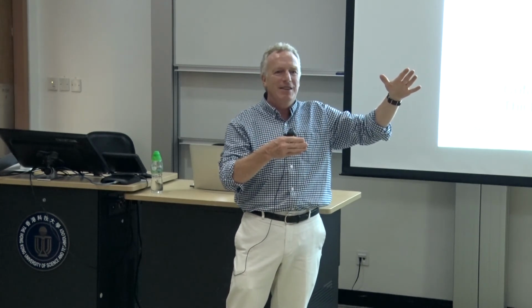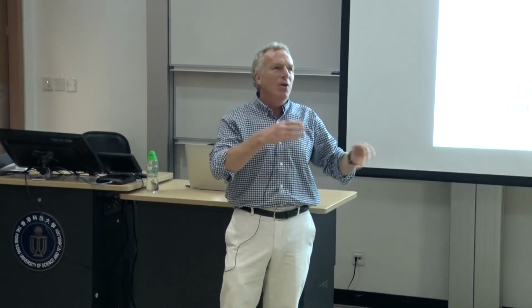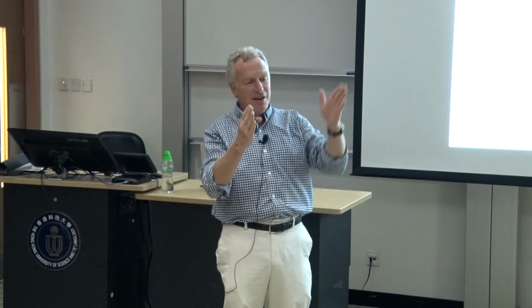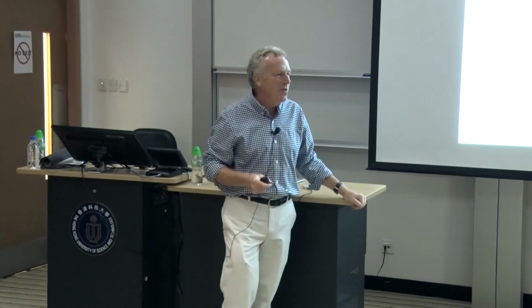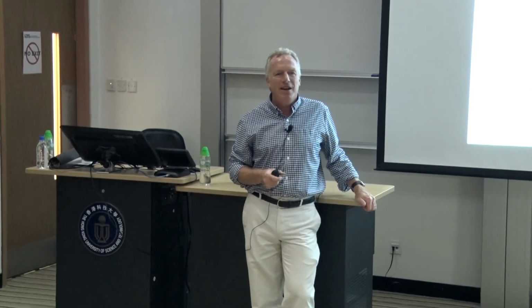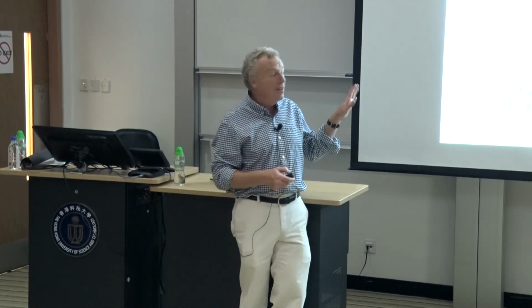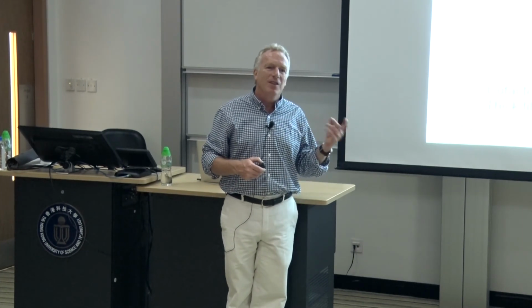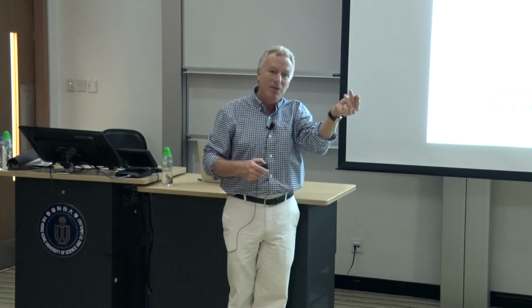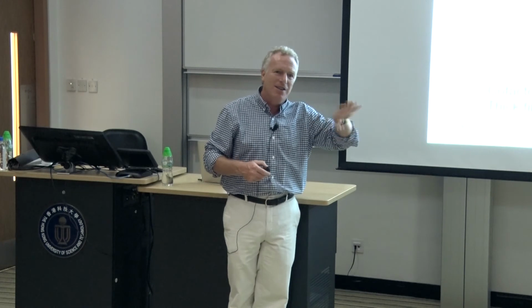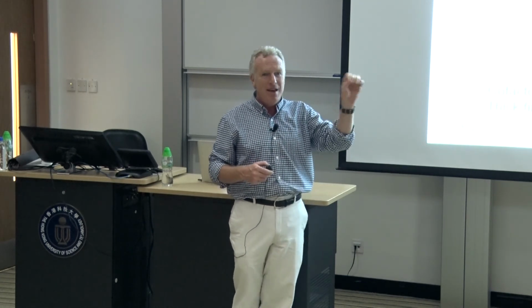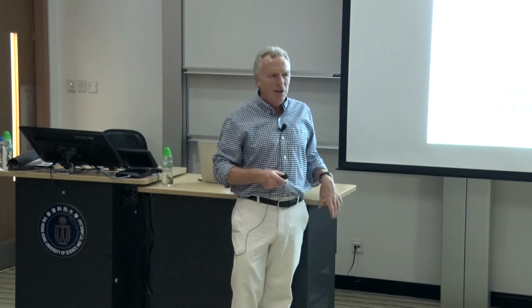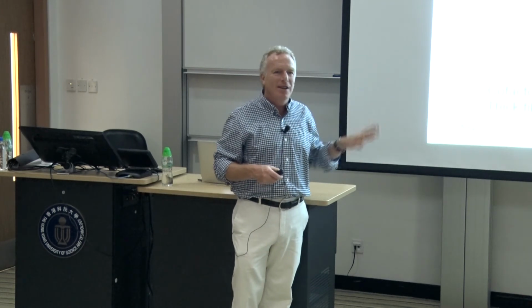You may well be right. But even when there's no volume change, these materials undergo large shear, and so there's still all the things you said about kinetics and so forth. You can make the same argument for the large shear too. And of course there are kinetic effects in these materials, and I didn't talk about them. There are aging effects that come from the fact that at finite temperature, atoms can switch position, especially under stress, and that can drive diffusion or local changes in local ordering, which is a very typical aging effect in these materials. I would say this is the more important thing, but that's definitely there.